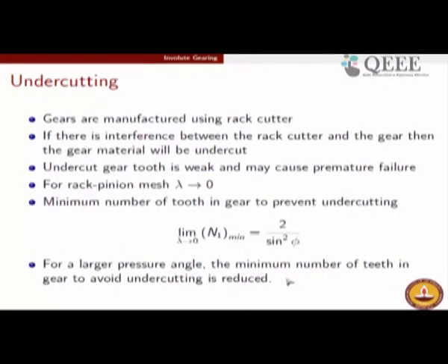But as we said, if you have a large pressure angle, then there is a large amount of wastage in terms of torque transmission, and it could also lead to axial deflection. So, you will have to take care of all that and arrive at a compromise value of phi. All this has been worked out, which is why we say that as per standards the pressure angles are one of those numbers: 20 degree, 25 degree or 14.5 degree.